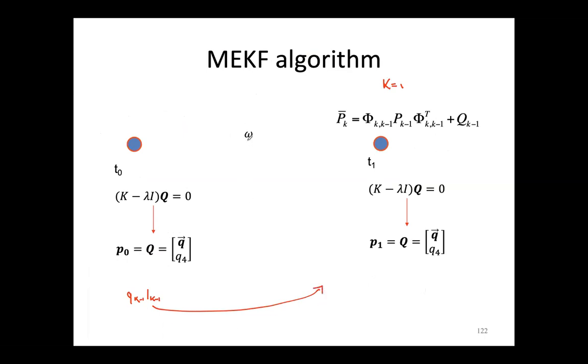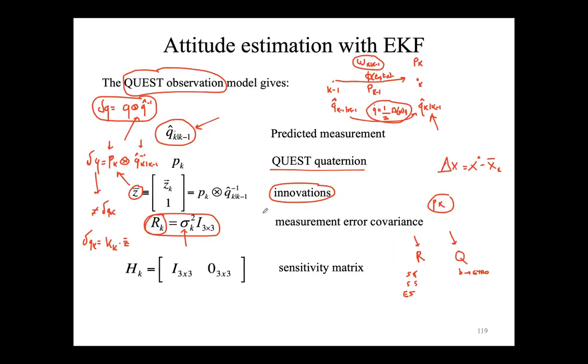However, this is not very useful, but we need to propagate this quaternion to this state here. So we're going to use the measurement from the gyroscope, omega, and so our quaternion dot equals 1/2 of big omega times Q, to determine our Q at a time k from k minus 1. This measurement corresponds to our prediction.